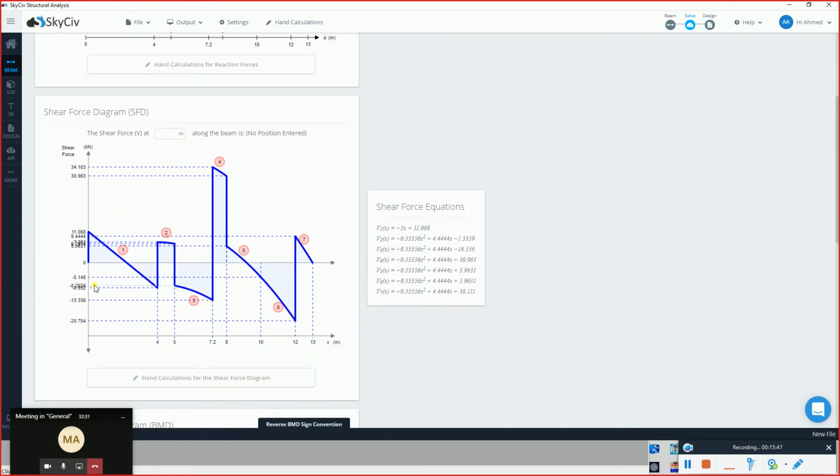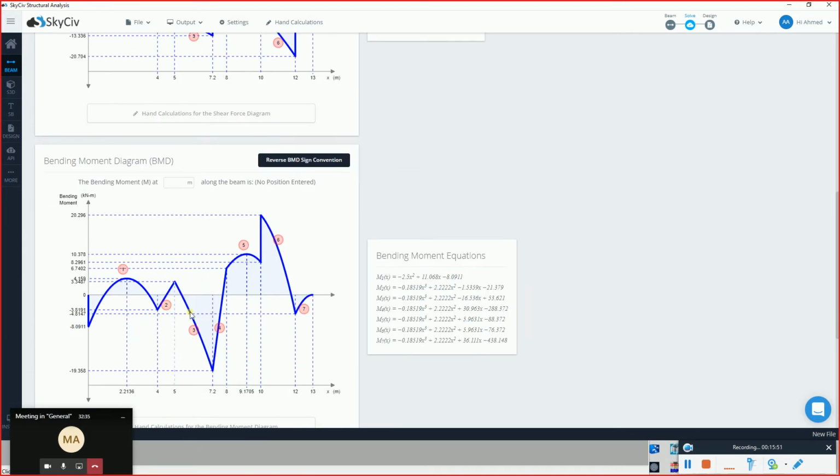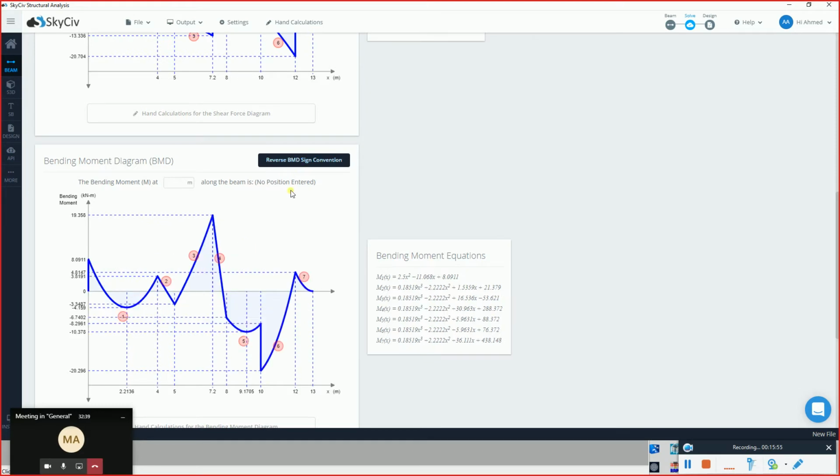This is the shear force diagram. Okay. And this is going to be your bending moment diagram, whether you want it to be downside or you want it to be the regular way. So going up because of the fixed support, down and then up. First support goes up and then down, and then because of the moment here it goes down and then once again up the support, and then in the free overhang, finally it ends up with zero.